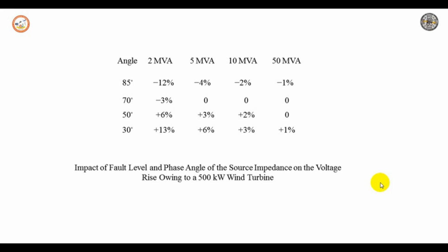Normally the measurement shows that load currents are strongly unbalanced, and this unbalance increases towards the end of the feeder. The strongly unbalanced load increases the risk of over voltage. Due to this distributed generation, the risk of under voltage will also increase due to high load. And also consider the small increase in the voltage along the feeder, with maximum voltage